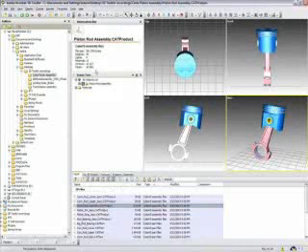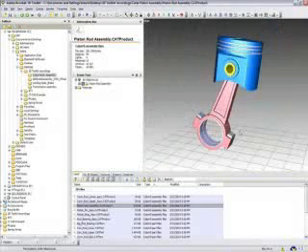The surface tolerance and normal deviation properties control how coarse or finely tessellated the solid geometry is when importing and changing a tessellated polygonal-based mesh. The default value for most of the CAD importers is 0.5 for the surface tolerance and 30 for normal deviation. When I import the model with these default settings, an assembly is generated with 18,000 polygons in the entire scene.